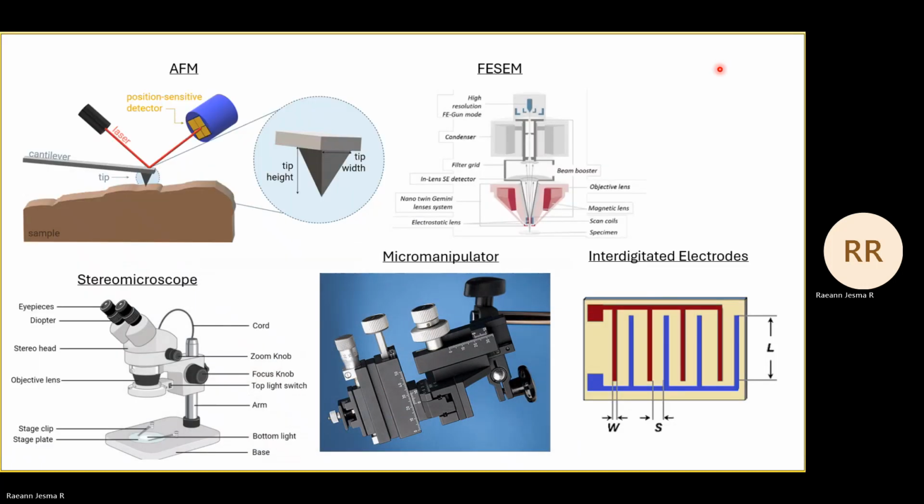By applying a suitable amount of voltage to the cantilever using a piezo scheme, you can make sure that the cantilever is in contact with the surface, then you can map the displacement. Other than this surface mapping, we can also make this cantilever bend in a particular way to apply a particular force on a sample. You can use it to stimulate cells and so on. So that is AFM. This is how the tip will look, a kind of pyramidal structure.